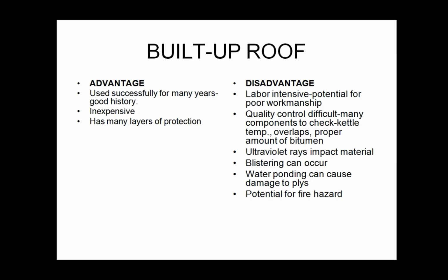And with the built-up roof, sometimes it's susceptible to heat and sunlight, where it could impact the material or cause blistering. And then when you get that, you're going to get some deformation in the material, which could lead to water ponding and could further damage the material just by having long-term water.